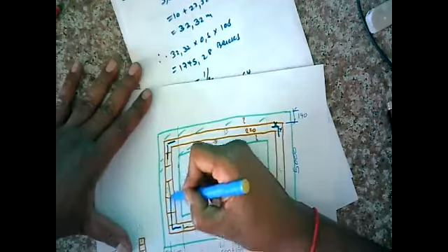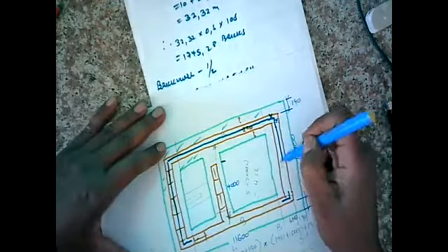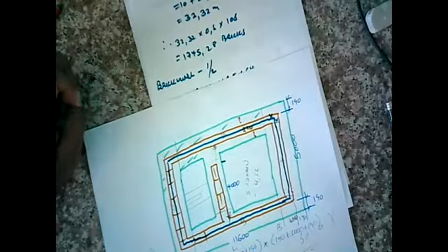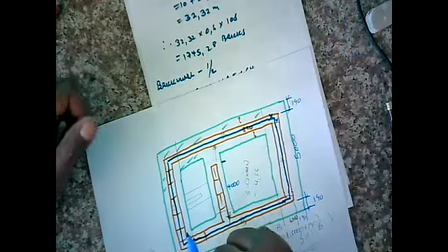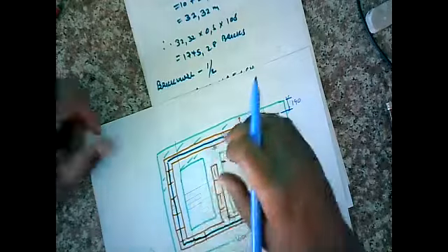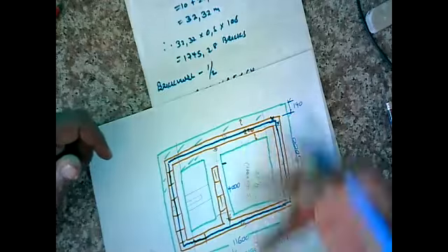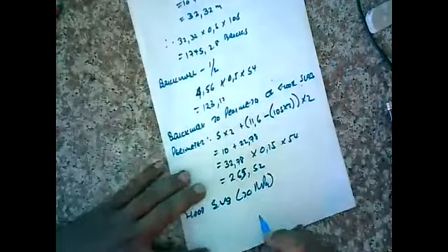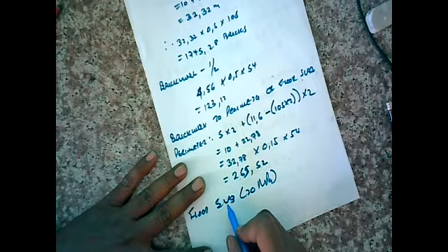So let's complete it all the way, basically all the blue lines, where everything within the blue line is now the area of our floor slab, and subsequently also the area of our mesh reinforcement and our soil poisoning. If we find the area of the floor slab, we actually find two more things. Easy marks there. Let's put the floor slab on. So we're saying 20 MPa, and we're getting a value of what?